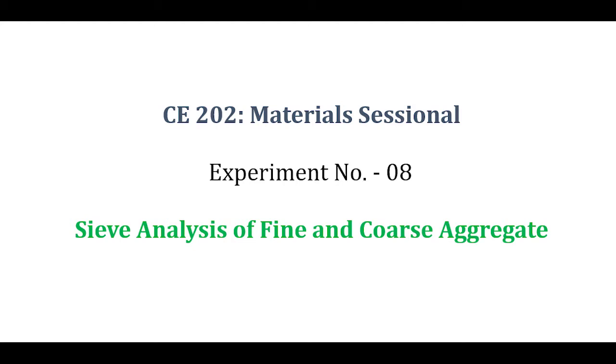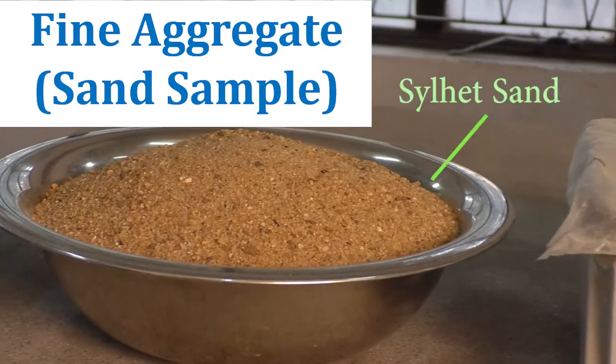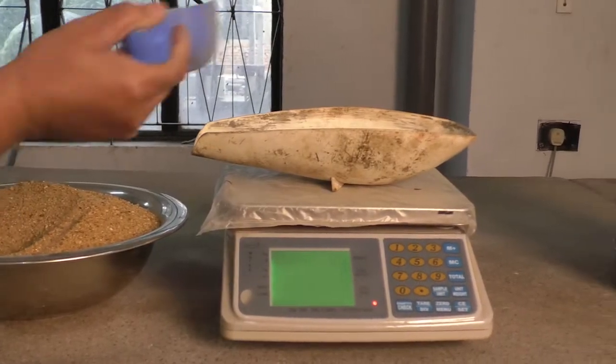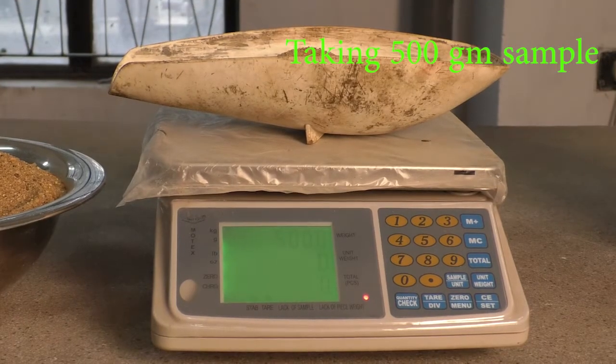Today we are going to demonstrate experiment number 8, sieve analysis of fine and coarse aggregate. First, the sieve analysis of fine aggregate is to be shown. As a fine aggregate sample, Sylhet sand has been taken here. This sample contains coarse type sand, for which a 500 gram sample has been taken for the test.